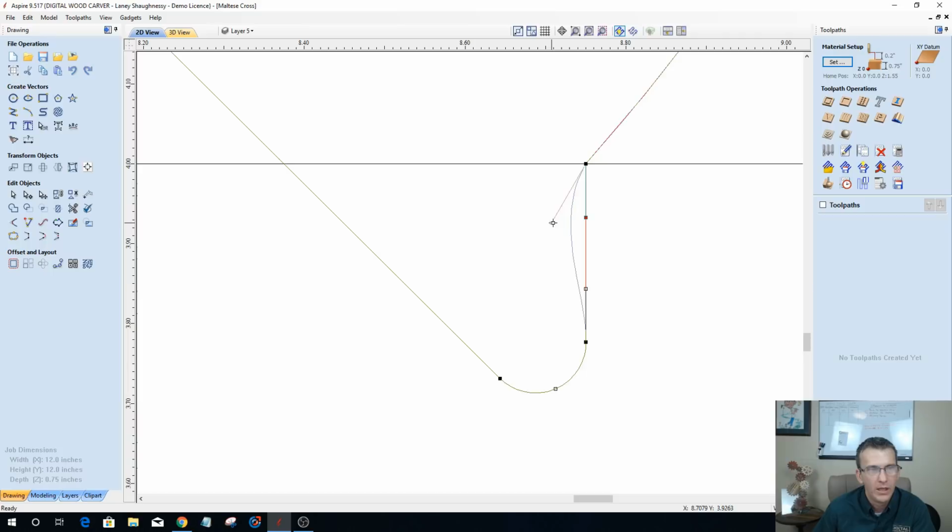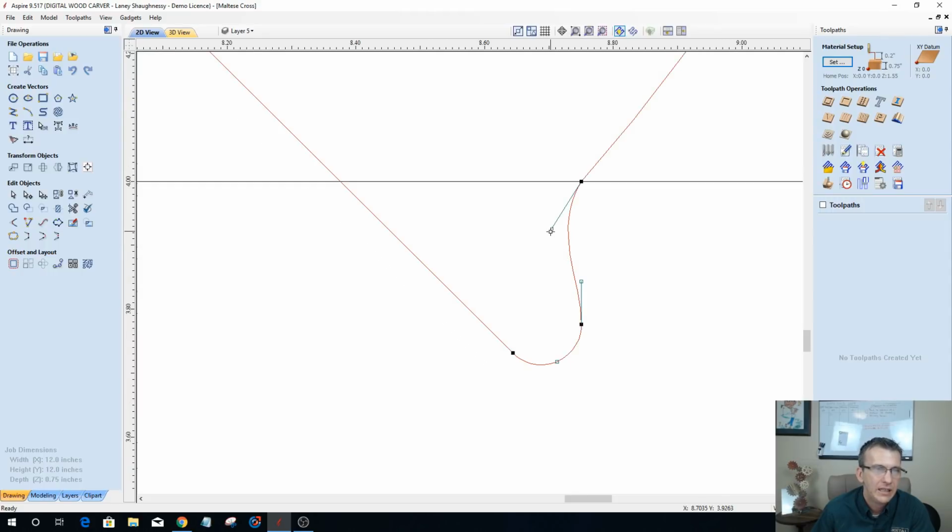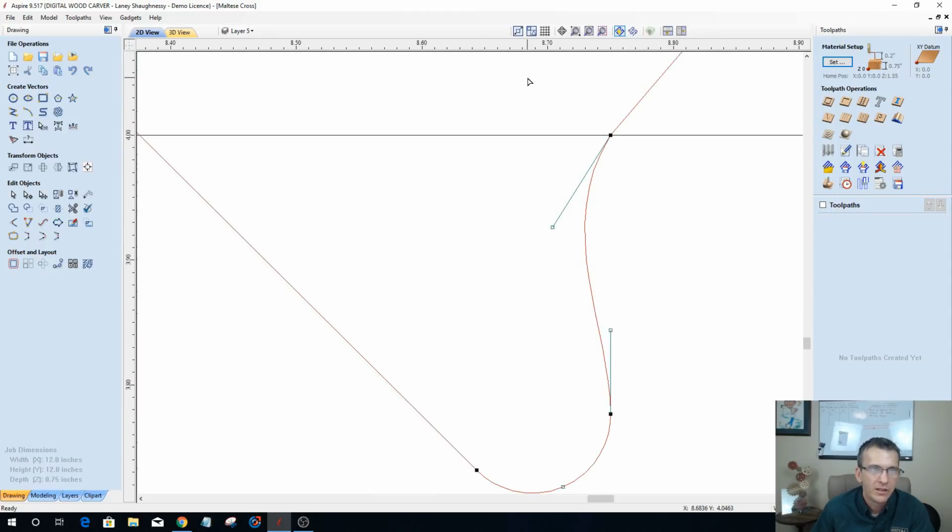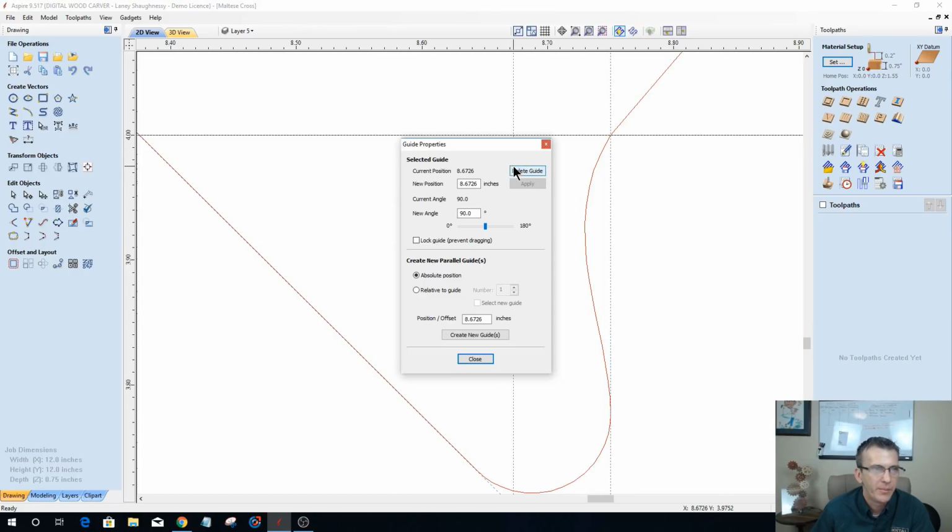Where I want to pull my anchor to is almost perfectly diagonal to my line here, this red line. I want that anchor to be an extension of that line. And if I need some help, I could pull a guideline in there and change my rotation of it. Let's pull it over here. I could go into the properties of that guideline and go 45 and click apply.